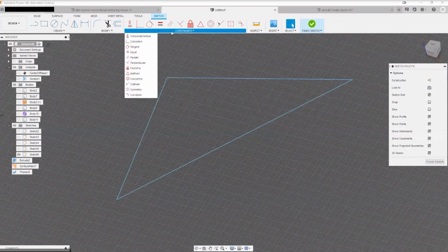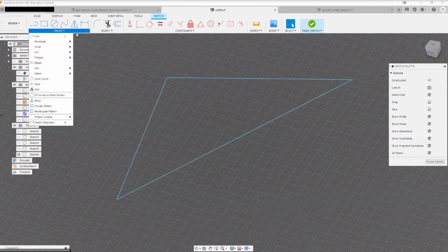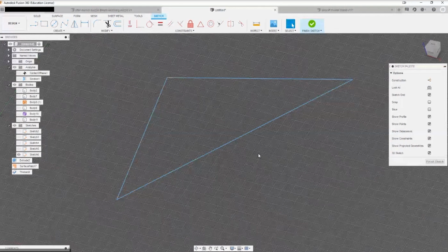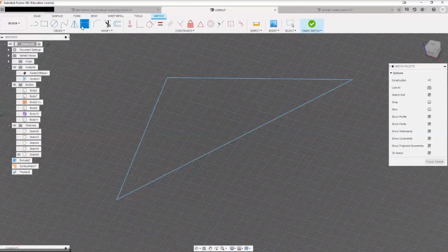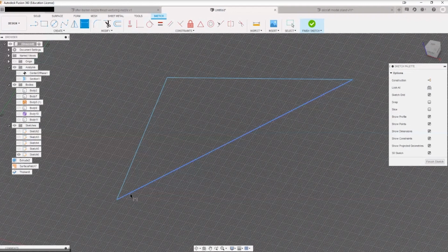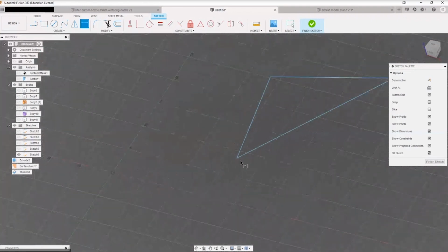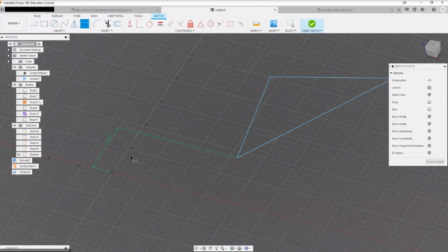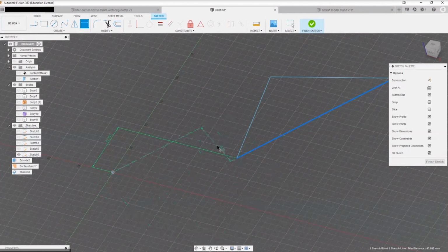But then there's also the dimensioning. The shortcut for that would be D. You can just hit D on the keyboard, and that brings up this little thing, so you don't have to click out there. So how do we constrain this point in the XY plane? Well, you want to specify first of all the Y direction, and the Z direction. It might take a little bit of wiggling about. Yeah, there we go. Okay, so now this point is constrained.